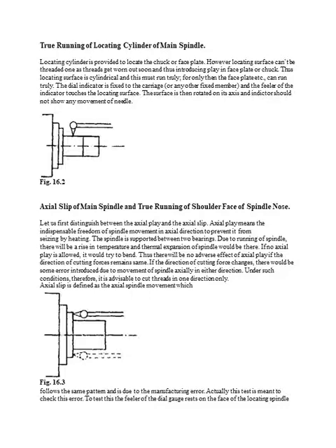The locating surface should be in a cylindrical shape. Then the dial gauge, you can see in the picture, is touching, and its plunger, that is the contact point, is called the feeler. The dial gauge is fixed on the carriage. The dial gauge is fitted using a dial stand.